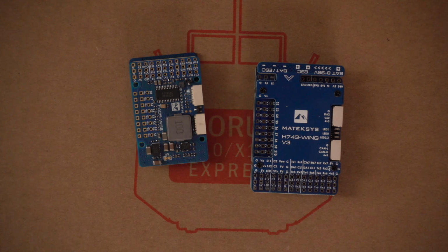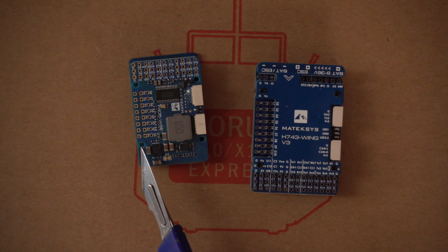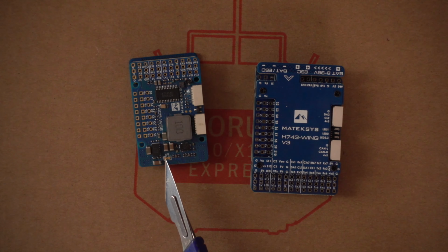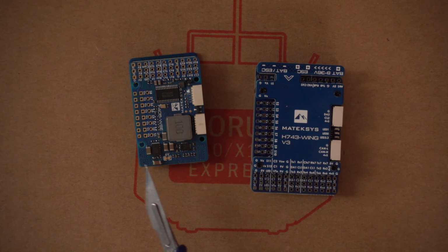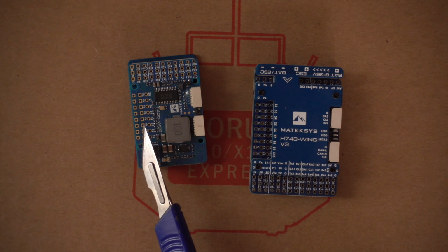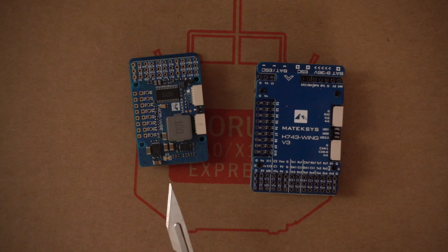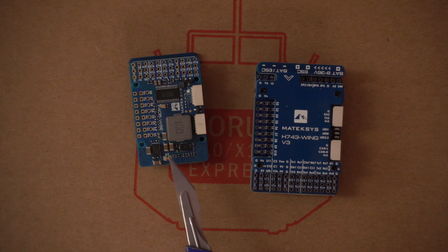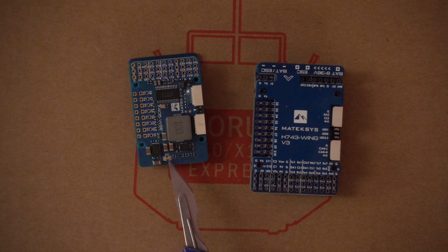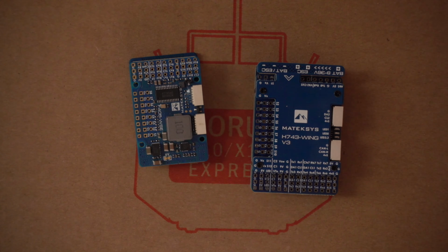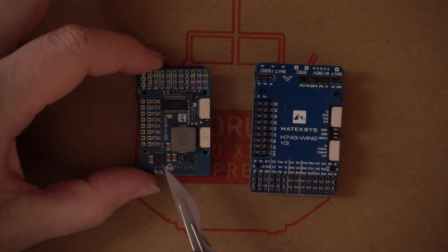Now, if you're following the kit version where we're selecting any of the servos I've put in the article, they can handle 6 volts absolutely fine. So I'd recommend bridging this. If the servo gets 6 volts, it instantly gains a bit of speed and a bit of torque. So it's well worth doing. If you're using the plug and play, I would recommend leaving it on 5 volts. So don't bridge that at all.